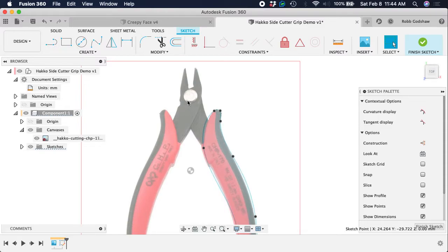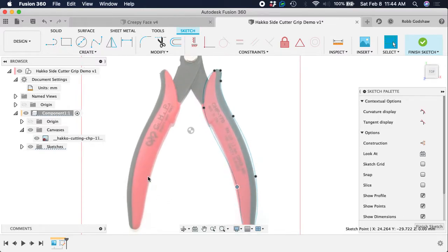Then they put the entire metal tool into an injection mold, into a molding machine, so they can injection mold the red plastic around the handle. So the steel handle probably has holes in it to make sure that it has a lot of surface area for the plastic to grab onto, and the plastic flows around the metal and actually surrounds it. But once that's done, they have to injection mold it once more to add the rubber. So they put the plastic and metal tool into another mold, and they injection mold the rubber.